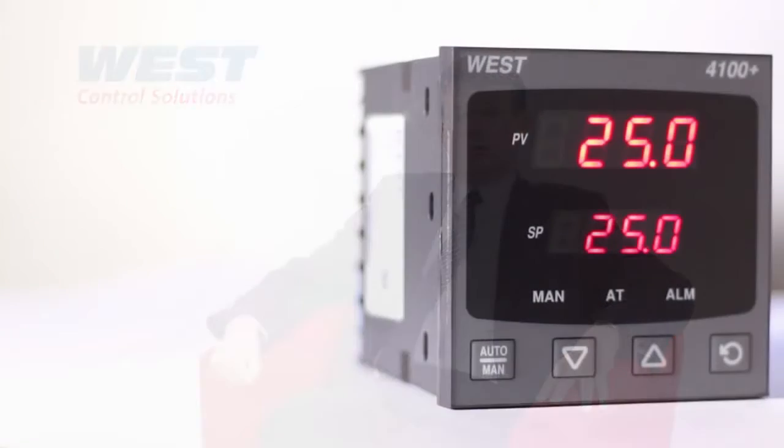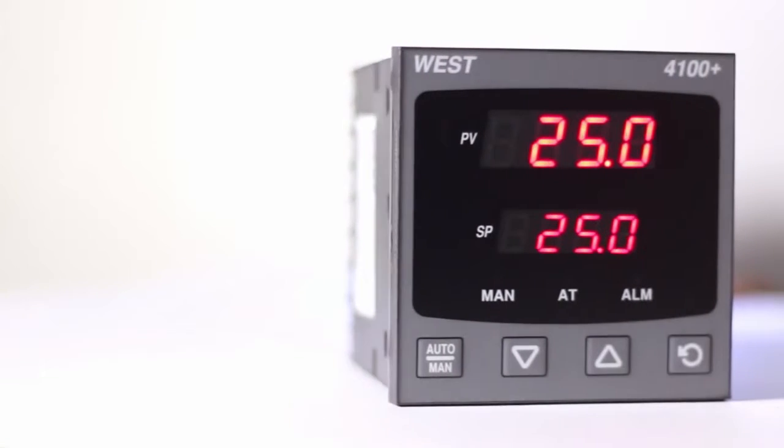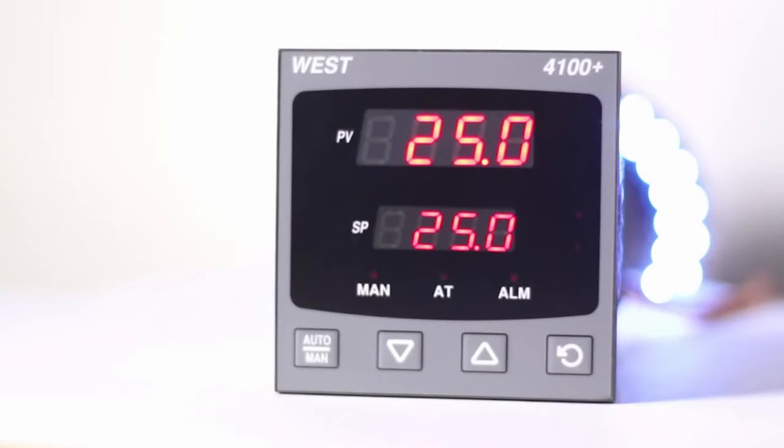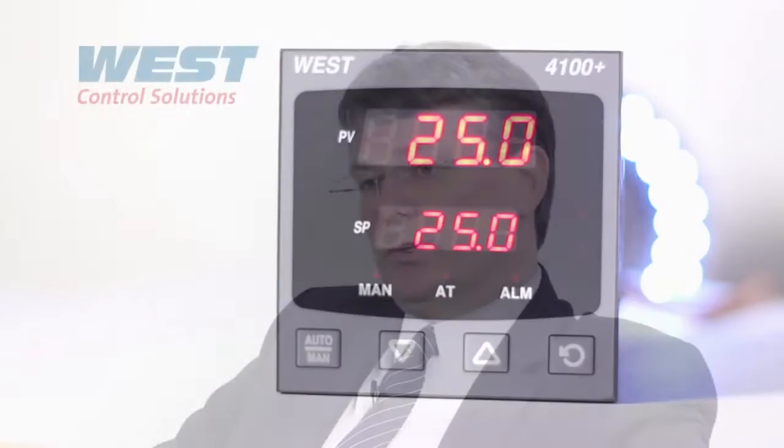As with many aspects of process control, compromise is needed. It's generally better to set the cycle time as long as you can get away with, but still have adequate control in your process. The exception to this is if your process is entirely solid state in nature, in which case you can probably set the cycle time much lower.